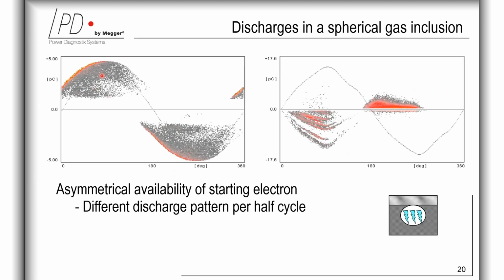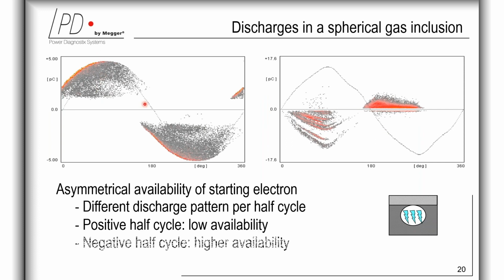And this pattern from the previous slide indicates a symmetrical pattern. And on the right side, here you see an asymmetrical pattern. The symmetrical pattern on the left belongs to an epoxy resin with a single void with average charge generation. However, this asymmetrical pattern on the right-hand side is an example of multiple voids. Here we do have up to 10 gas inclusions, which you can also separate visually on the positive half cycle due to the higher amplitude. And as said, it's relatively easier to distinguish.